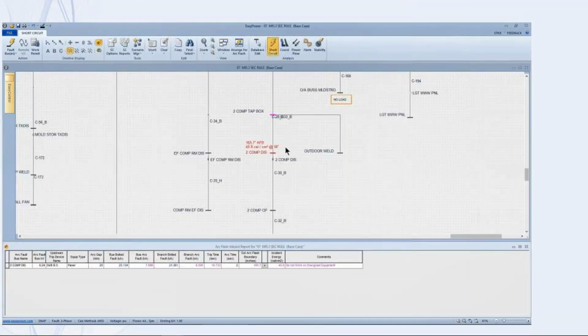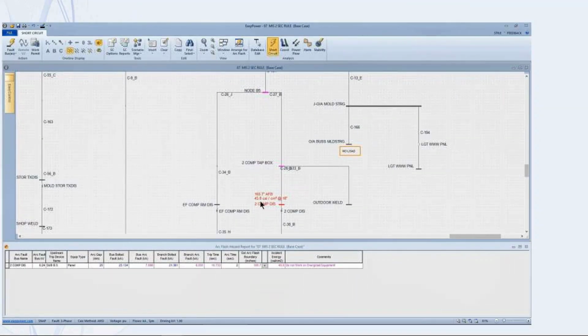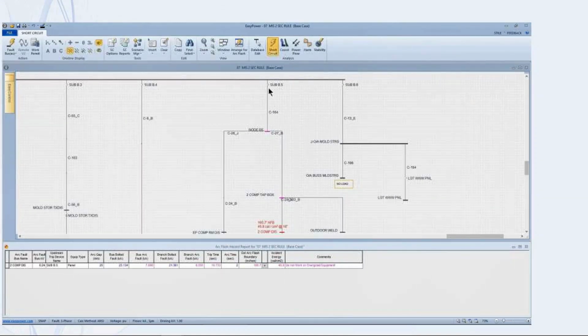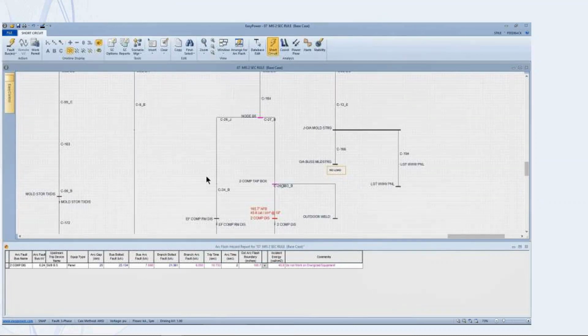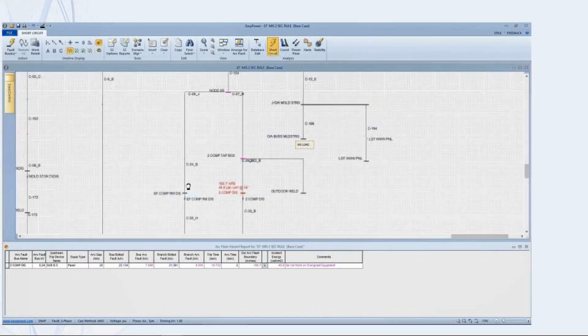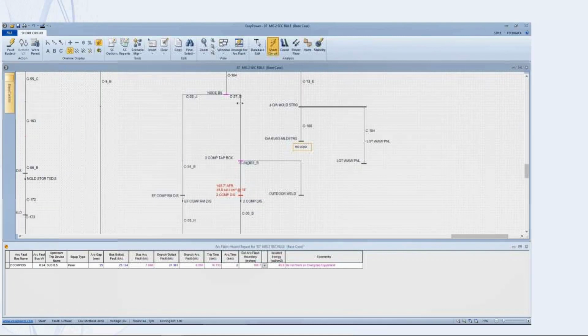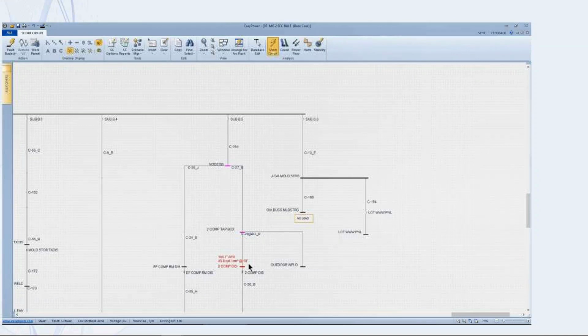Now this is a bus that's showing high incident energy, and I know it's limited to 2 seconds, and we're showing it's fed by a breaker, and the arcing current looks like it's 7,000 amps, which is substantial even in a 240 volt system. So my question is, why is it taking so long? If we're limiting this to 2 seconds and really it's going to take 10 seconds for the protective device to trip, why? What's the problem?